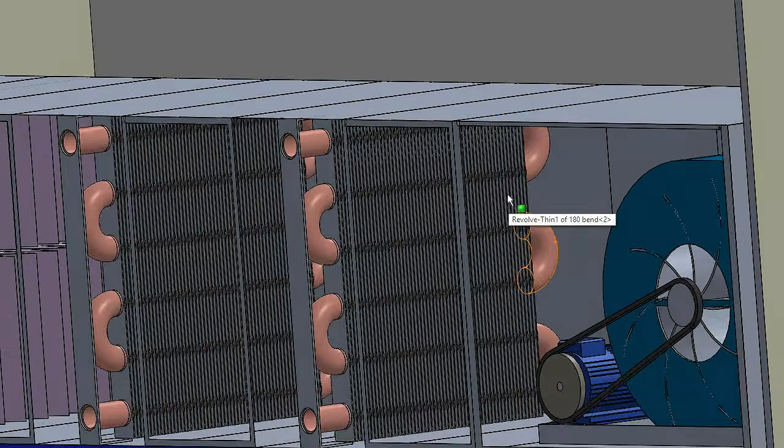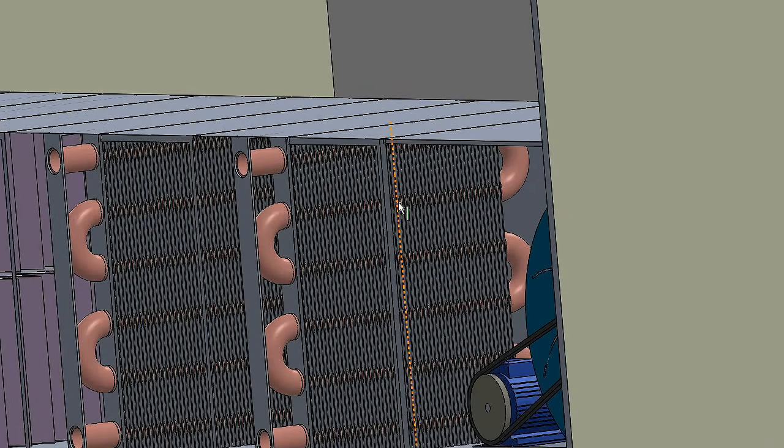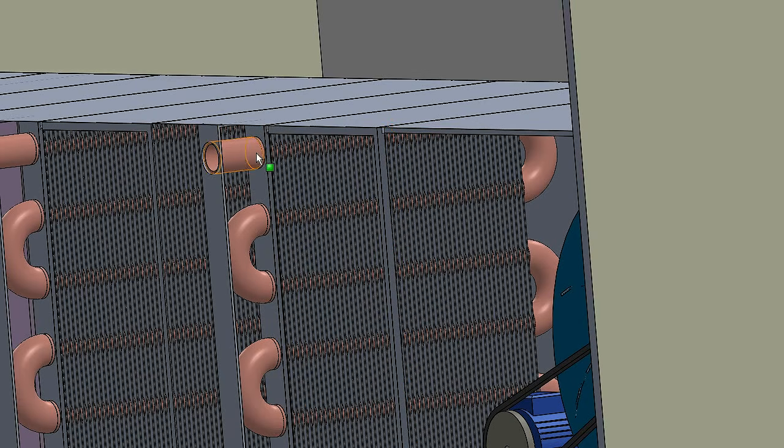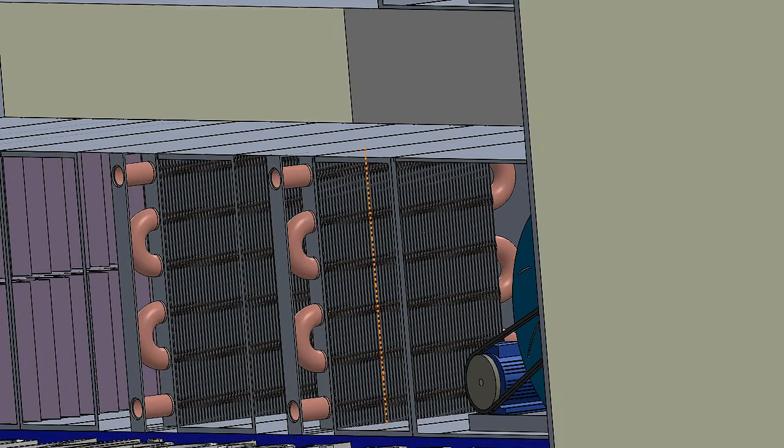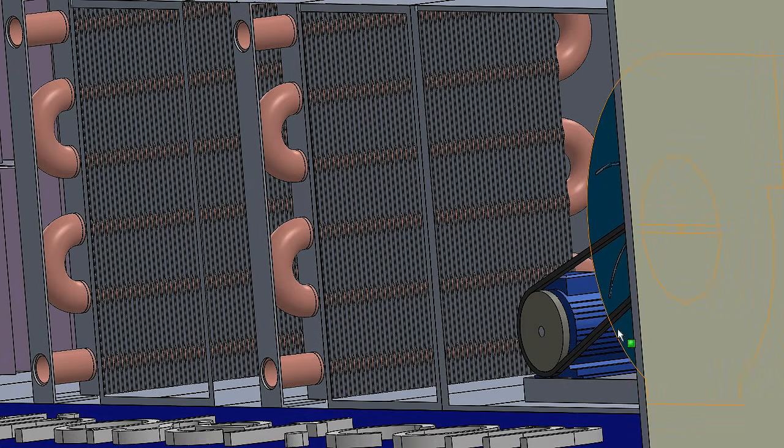But as you should be able to see here, the coil is configured so the pipe inside runs in this configuration all the way around until, well, in fact it runs the other way, but same difference, until it exits. So the pipe is going all the way through there, and inside there is the heated or cooled water, and maybe steam. You could have steam on the hot side as well, on the heating coil.